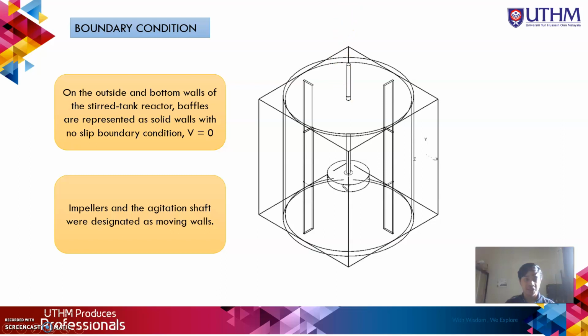Next is the boundary condition. On the outside and the bottom walls of the stirred tank reactor, baffles are represented as solid walls with no slip boundary condition, which is V equal to 0. The impeller and the agitating shaft were designed as the moving walls in the stirred tank.